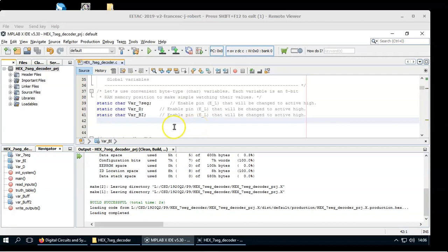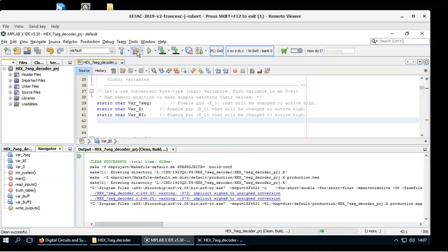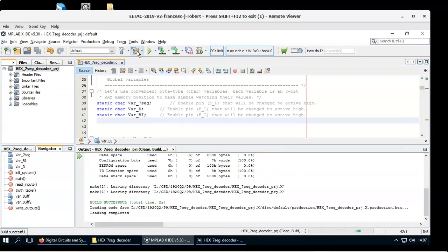There is something else that I have to tell you that sometimes you ask a lot about, because it seems that it's not working. When you do that way of going step by step, for example, now if you try to add the variable D or the variable 7 segments, and perhaps, who knows, later, depending on the way that you are organizing this, the bar A, the bar B, the bar C for every single segment, as you like. When you do that, think of adding new variables in the code and compiling them all, cleaning the previous version of the compiled code and rerunning and regenerating a new compilation.